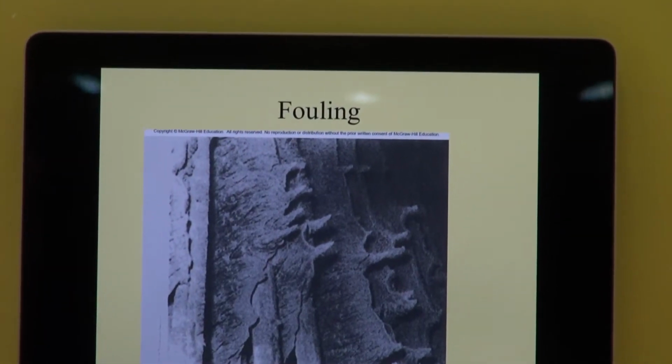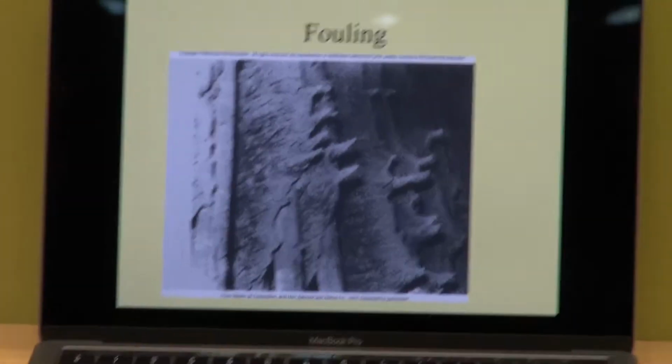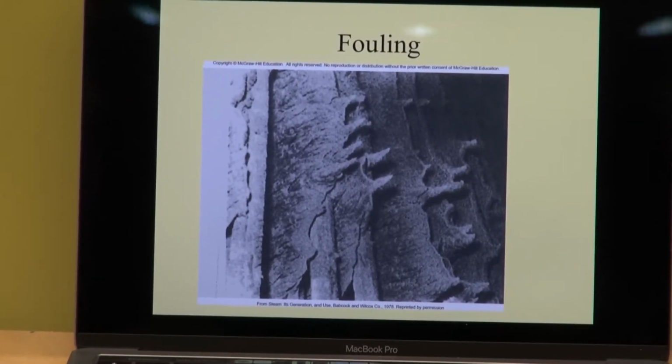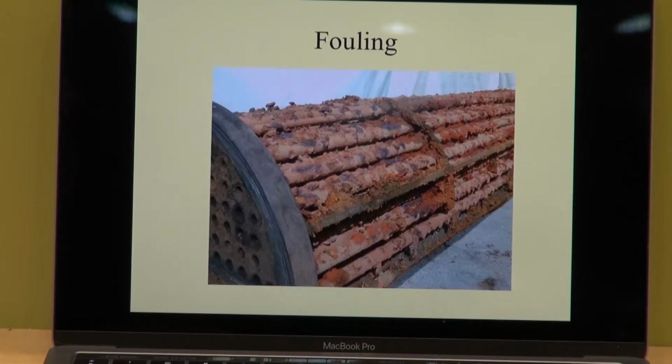You can all see it in many of the kettles that you use to boil water, especially in very specific parts of the country. That scale can build up to quite a few millimeters, sometimes 10, 20 millimeters. And then also in the hot water storage tanks, the geysers, they can really build up there. This is typically what can happen in a shell and tube heat exchanger.